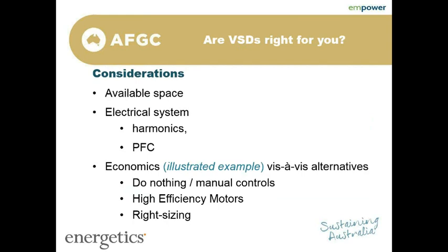And so the other thing to consider is whether it's right for your site, your situation. They're quite versatile, VSDs. There's not many AC induction motors they're not suitable for. There's just a few key considerations there. The main one outside of the technical considerations is the economics of it, which I'll get to in a second. But just some considerations are available space.